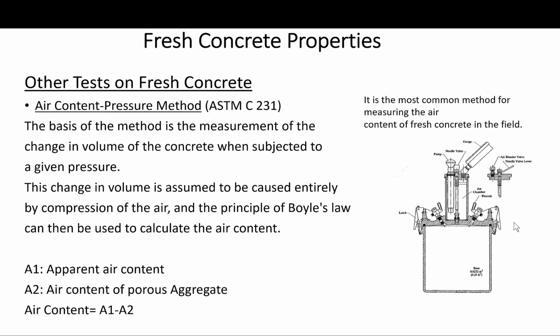It should be noted that these tests measure only, as we said, the total volume of the air in concrete. They yield no information about the nature of the air void system. But as we have seen in previous discussions, it is the nature of the air void system, meaning the pore size and the pore spacing, that really determine the durability of the concrete.